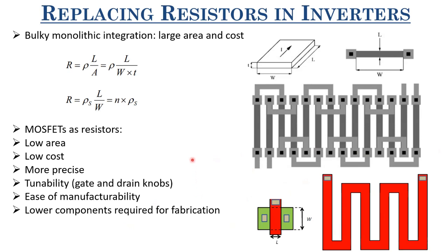So now that we know that by replacing resistors via MOSFET in your chips, you can reduce the area cost and you can also reduce the static dissipation, let us go ahead and see what are the different available options for realizing these resistors. And then after analyzing those different options for resistances, we'll see how exactly these inverters will work with N MOSFET as the primary element and these different implementations of resistors using MOSFET as the load.